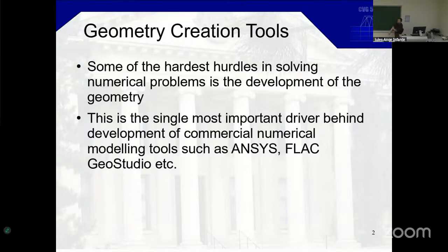So when you get the software package, like finite element method to solve it, solving the finite element method is usually fairly simple. I mean, there's complexities, like when you start talking about soil plasticity, then at each step you need to check where you are in the state of stress, and it will change the stress-strain relationships depending on where you are. So you need to keep a history, and that adds some complexity. But in essence, between each step, all you do is invert a matrix